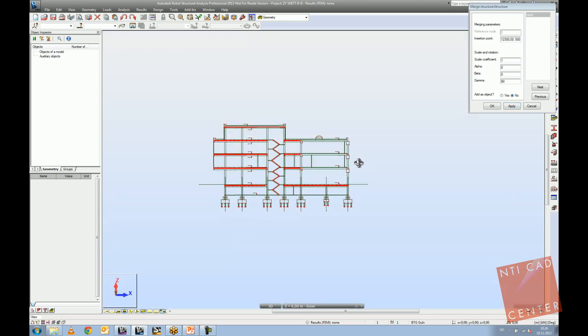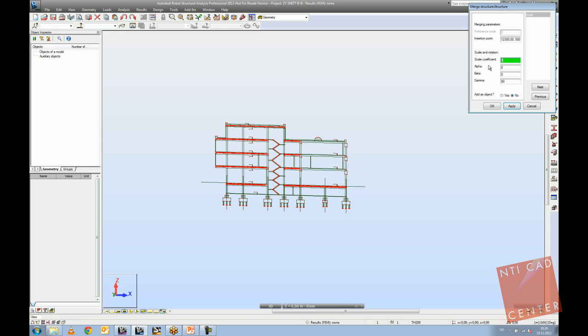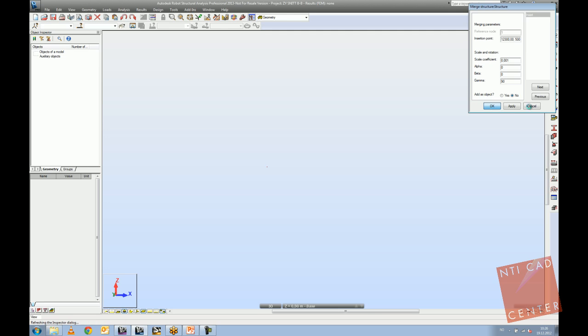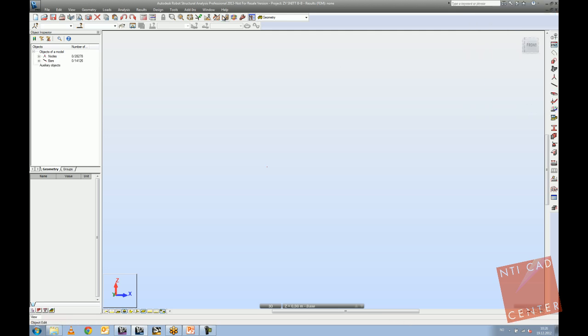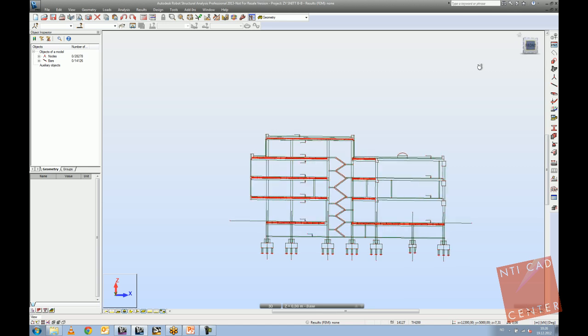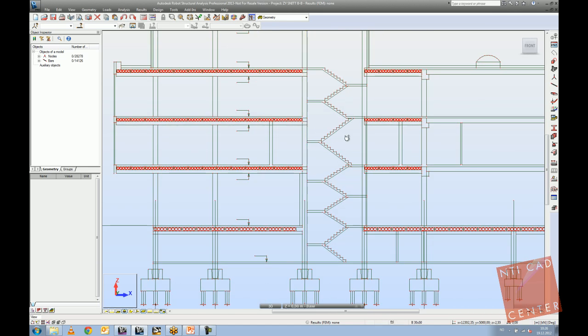I should be able to easily flip it. I can specify the start axis, and then in the end I believe I need to specify a scale of 0.001 so that it's not meters but millimeters. Clicking on OK, and searching for the model, and here you have it.